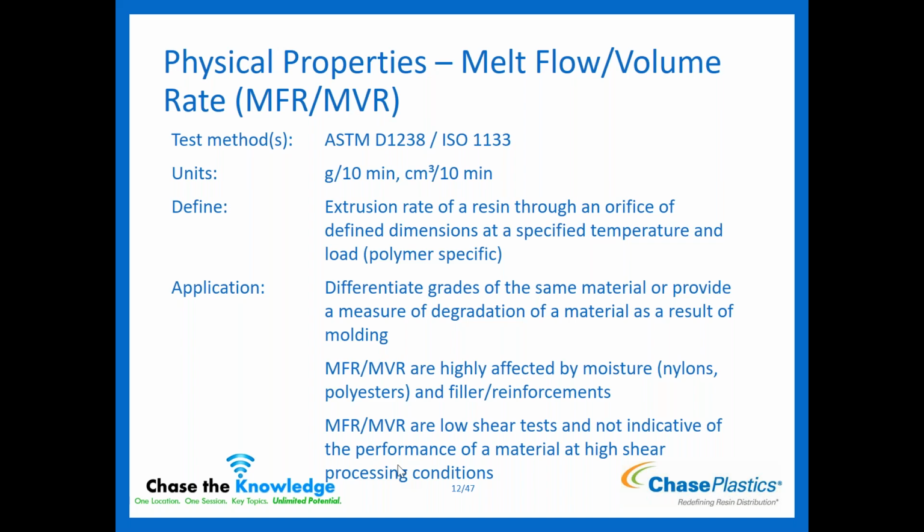The other thing to note is that your melt flow rates and melt volume rates, they're very affected by moisture in the material. So that's why you'll see materials like nylons or polyesters, PBTs, they're not going to have melt flow necessarily on the data sheet or as a test, because even the slight difference in decimal percentage moisture is going to highly affect the melt flow rate you're going to get.